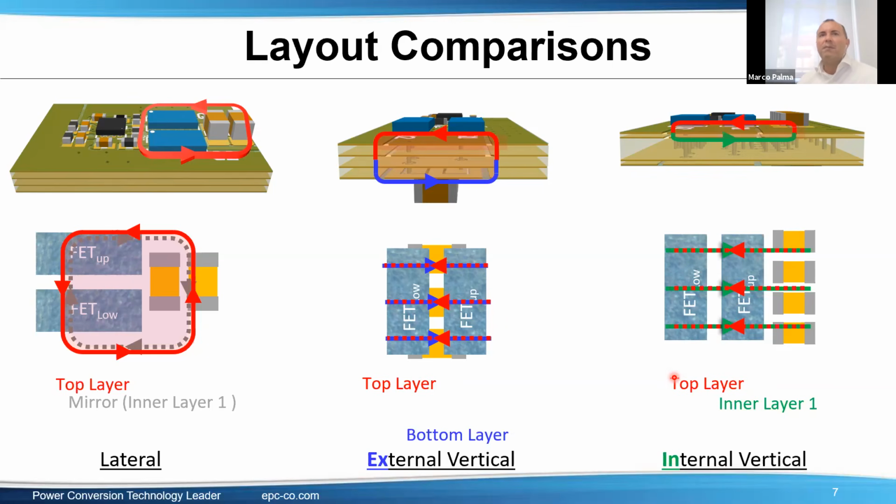Imagine this is the gate driver. If you put the gate driver on the bottom, you will have some inductance before arriving at the gate, and as we showed, inductance in the gate loop is detrimental. However, I did it, and if you need to do it, as long as you place the gate driver to minimize the distance of this gate going and return, then it's feasible.